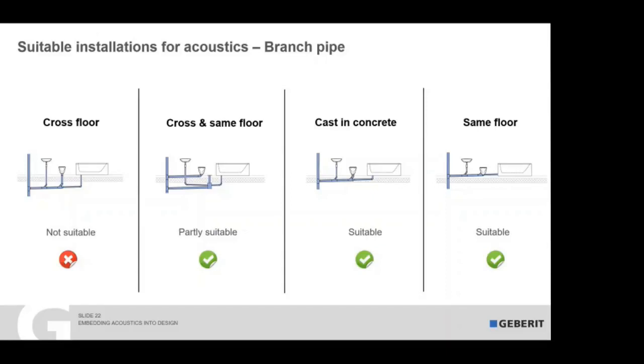Yes, so the pipe-in-pipe system, I know those systems, and those are mostly for very delicate buildings where, for example, there is electricity or special laboratories. But I would say if you use a good pipe material, which is hard to break and very rigid, I think it's not necessary to use such a pipe-in-pipe system. And of course, it would be very expensive. So for the noise, I think it would not have a big influence. It depends more on the pipe material and on the fittings you use. But of course, on leakage, it would have a good effect if you make a proper installation. But yeah, we think that the HDPE anyway is the best material for installation, and you would not have any leakage with a proper installation.